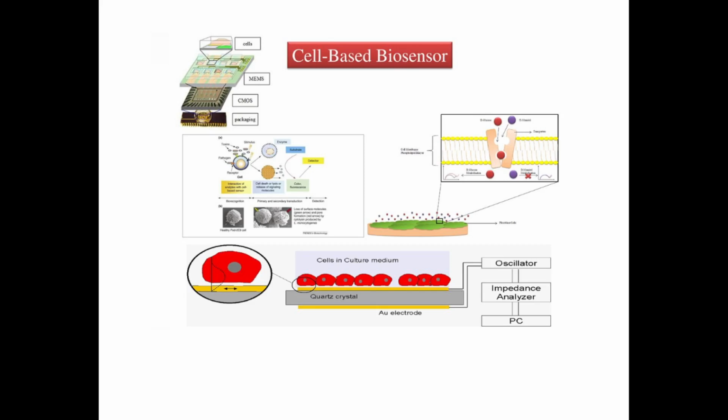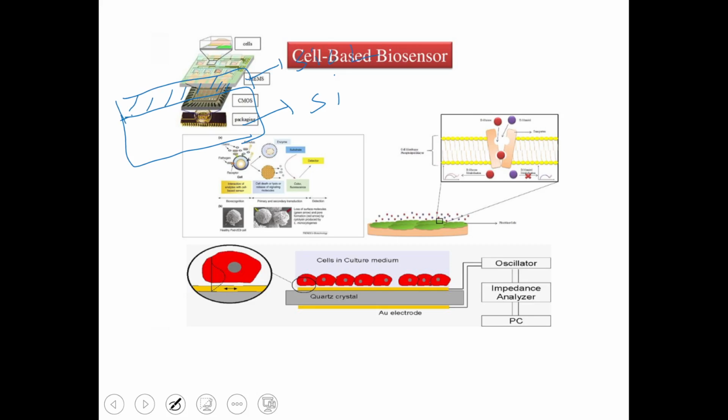So what will happen? We want to make the pressure sensors, for cell-based sensor design. Previously you can see the step where I have taken the silicon substrate here. This is the silicon. Then I have grown the oxide layer here, Si and SiO2. Next step, what will I do? I want to sense the pressure, so I want to choose the materials which sense the pressure.